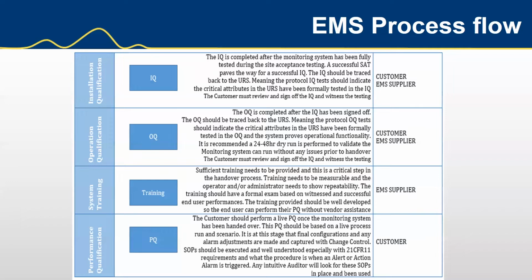And I always would like during the IQ and OQ stages for the customer to be really involved. You don't have to have a witness for IQ and OQ, but I would recommend doing so. Not only do you witness what's going on and sign it off, you can also get some great training during the IQ and OQ, because during these stages, we're going to go through some of the operation of the software, the hardware, and it's a really great way to understand the system. And you've got those documents which will show you how to do X, Y, and Z, kind of like a manual in itself.